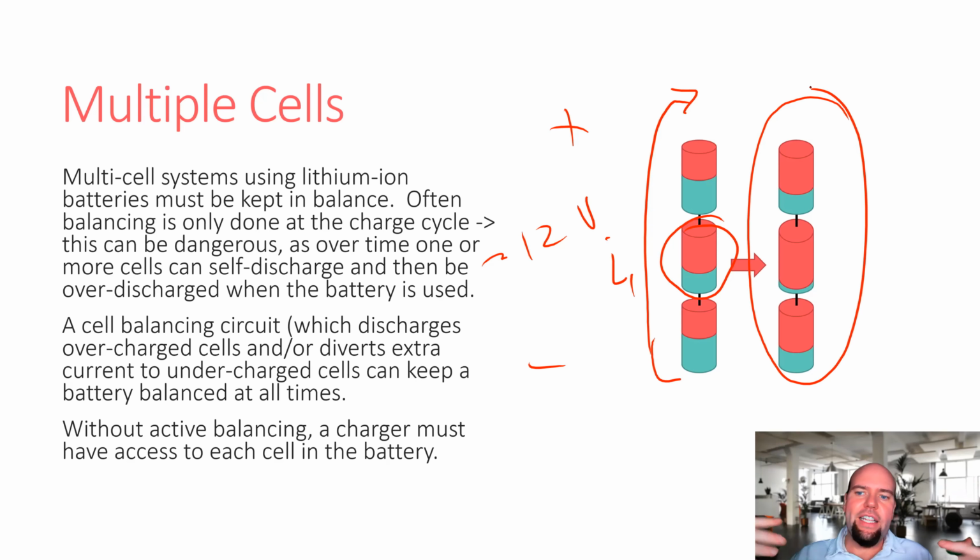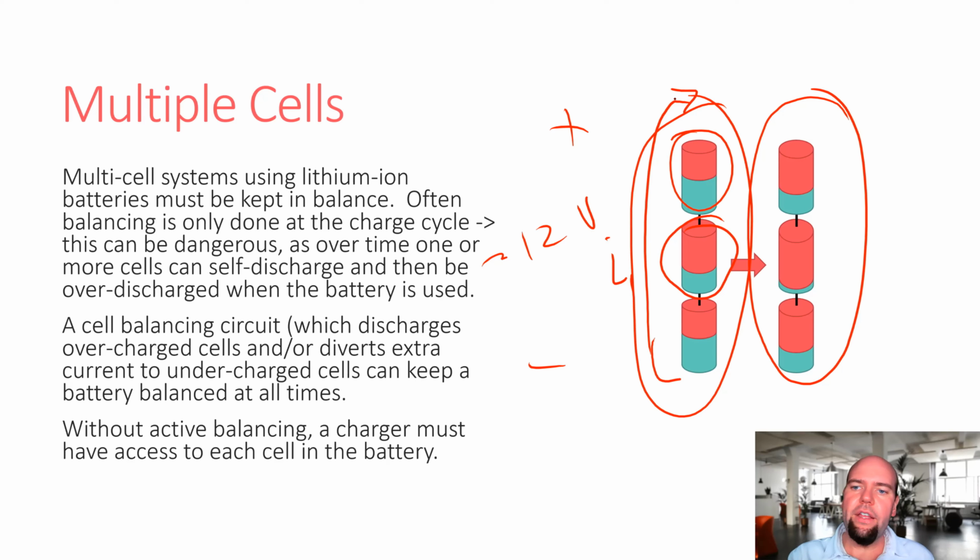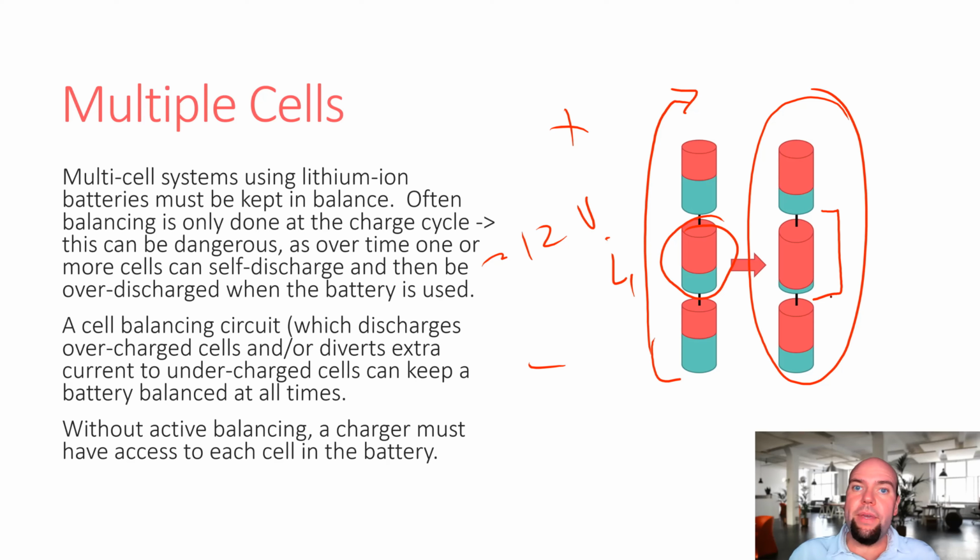battery, a battery is technically a collection of cells. Sometimes we use the term battery to refer to a single cell, but technically, the term battery refers to a collection of cells. So this would be a cell and this would be a battery. But as this battery discharges, this one little weak cell in the middle is going to be completely depleted before the others. So these two will still have energy, whereas this middle one will be completely depleted.